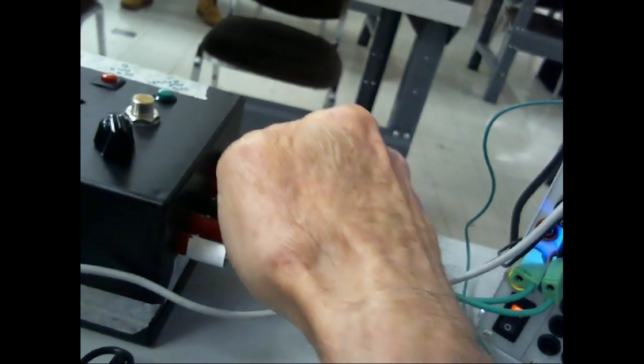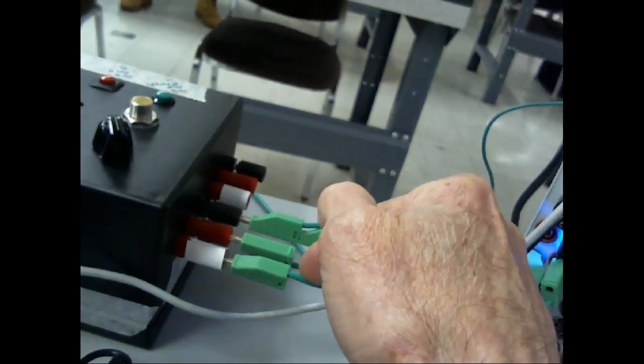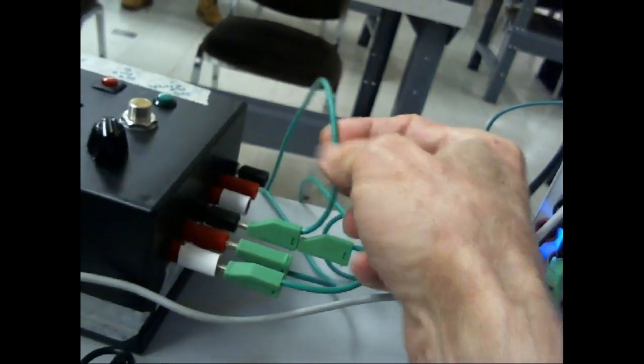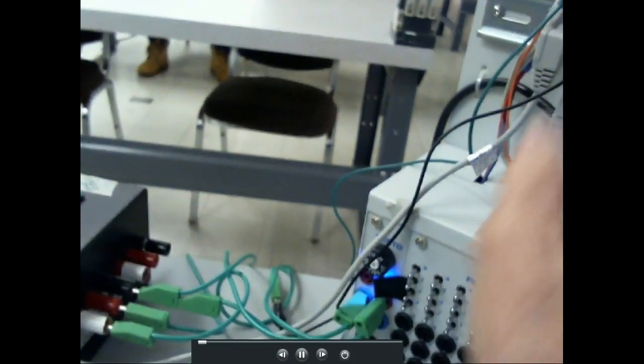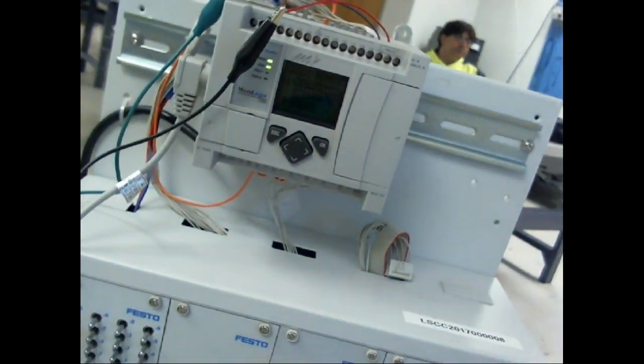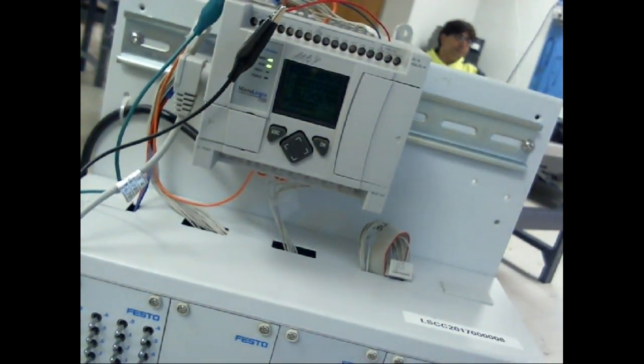So this will go to one side of the pot, this will go to the other side of the pot, and then this would be my signal source. What I have to do is run my common up to the black lead right here of my analog input. But this would be any analog sensor, right? Like a temperature sensor or a pressure sensor gives me an analog output. For this one, that analog output would have to be in voltage, 0 to 10 volts, right? 0 for minimum and 10 for maximum.